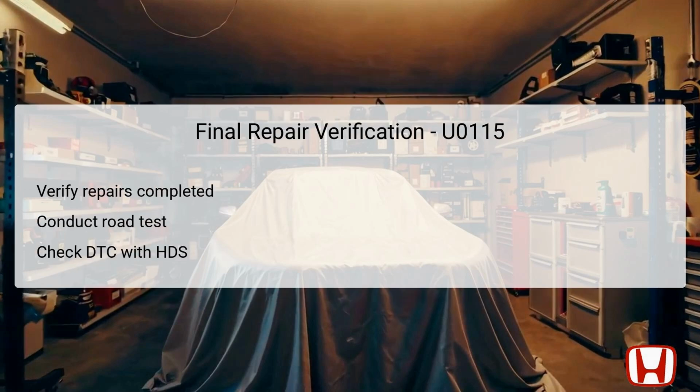After completing the necessary repair steps for DTC U0115, it is crucial to perform a final verification of the repairs. Start by ensuring that all identified issues, such as faulty wiring or loose connections, are properly addressed. Conduct a road test to observe the vehicle's performance and ensure smooth shifting and acceleration. During this testing phase, continuously monitor for the reappearance of the check engine light or any pending DTCs.